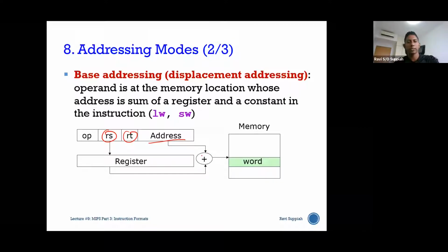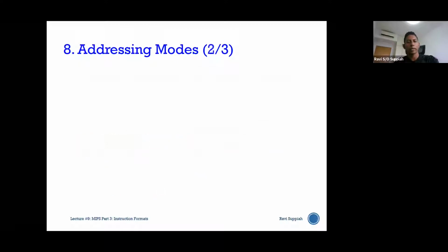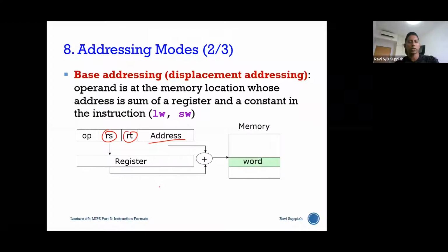But the main difference is that over here we are performing an operation directly on the data together with the immediate value, and that is a data operation. That result is again stored back within the register itself. Whereas in memory access instructions, the operation we're carrying out is actually to point to some memory location, to point to an address in the memory.